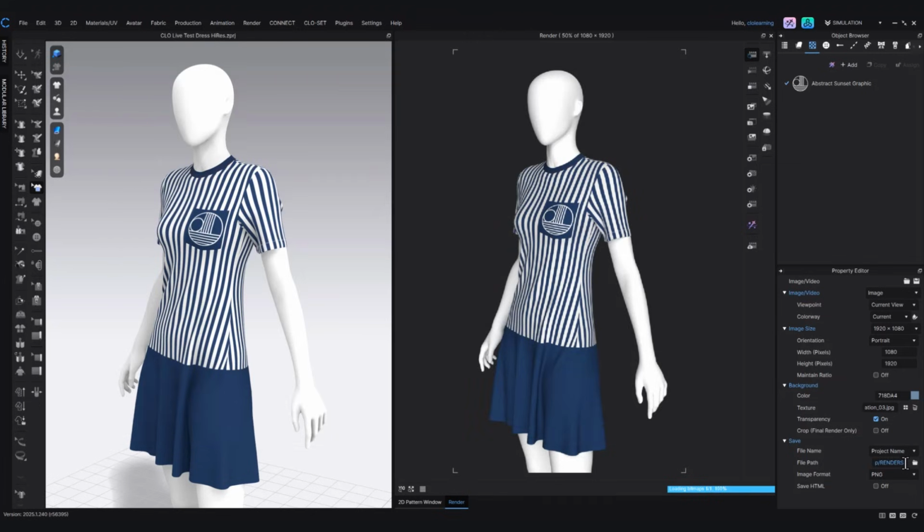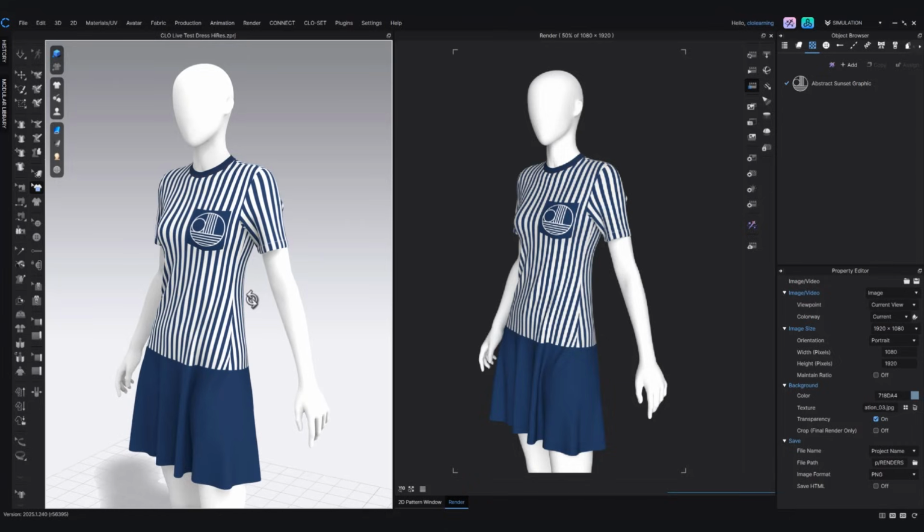And lastly, again, what I just changed, PNG or JPEG. I selected PNG. So as long as I have an angle on my camera that I've selected, I've set up my lights, I've set up my camera, I'm ready to go. Lights, camera, action. What we do need to do is click Stop Render. This is going to stop our interactive render. You'll notice that if I change my camera view here and rotate, it's not rotating in the render window anymore. And finally, we click Play.